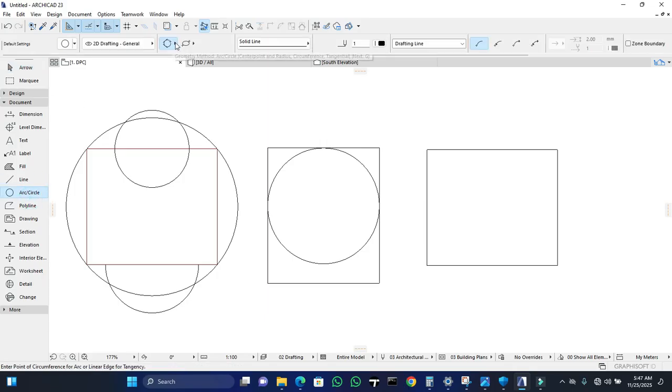You can go back to the initial one, which is circle and radius. Then there are other options here. This is ellipse, which is 2 points. An ellipse has 2 radius. So the first way to draw an ellipse is to specify the 2 edges. So click on that and say that's the first edge, that's the second edge. You've drawn one.